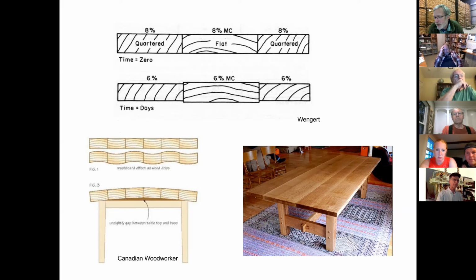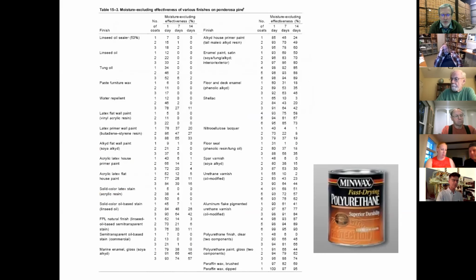Well, it doesn't matter what species, it's the quarter sawn boards that are going to be the most dimensionally stable, right? Generally speaking, and you won't like this, but really wide planks are going to move more than a bunch of narrow planks glued together. Why is that? Because you're typically going to have more curvature, more difference in the growth rings, looking at it from the end in a wide piece than in shorter pieces all glued together, right? And so that's something to be aware of and wary of as you move through.